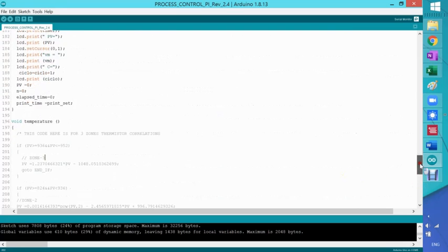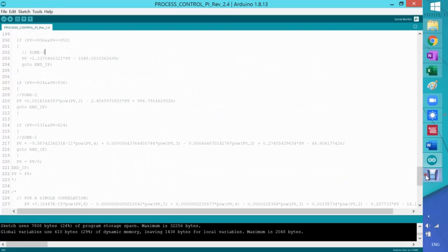If the number is not within the 3 zones that I want, like for example, I divide by 0 here, that will cause some commotion, and you will have to look at what's going to happen with that. I mean, that's one way to do it. Just to entertain the situation that the ADC value that is coming from the Arduino cannot be correlated to any temperature. Okay?